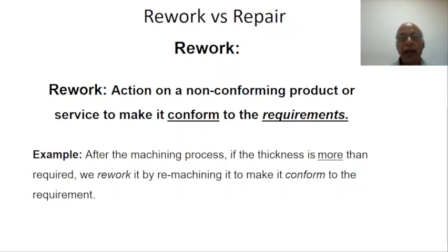Rework is action on a non-conforming product or service to make it conform to the requirements of the customer. For better understanding, here is a simple example. Suppose after the machining process of a part, we find the thickness is out of spec, more than the upper limit as per the size tolerance. So we rework it by remachining to make it conform to the requirement, or whatever tolerance is provided on the thickness of the part.